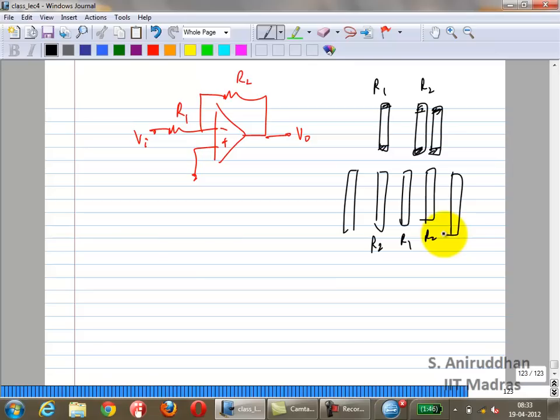Right? The wider you make the resistors, you would reduce random mismatches. Remember that the random mismatches depend on the overall width and length of the area of the device. So the wider you make it, you will make the resistors match better. Okay. So why not make them extremely wide, 10 microns, 20 microns wide?